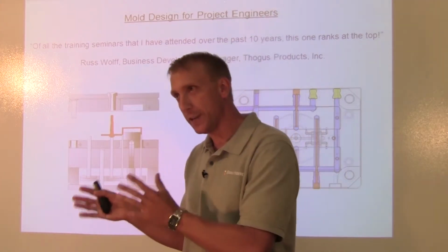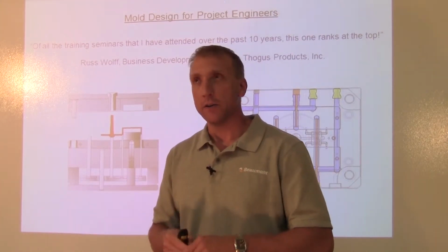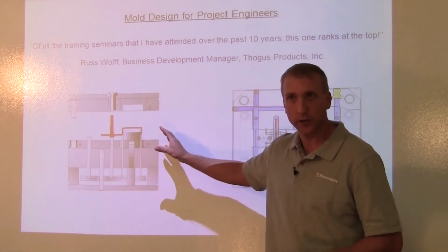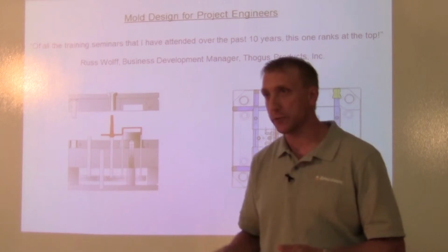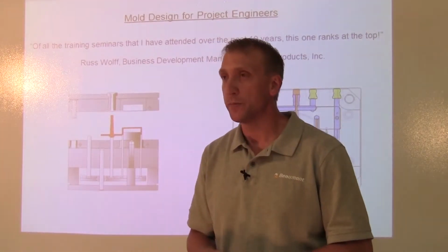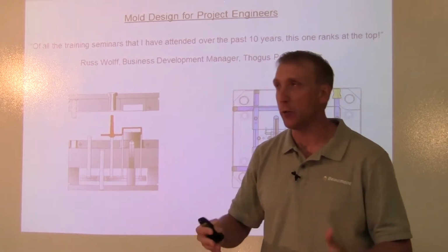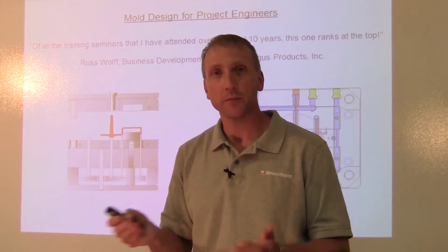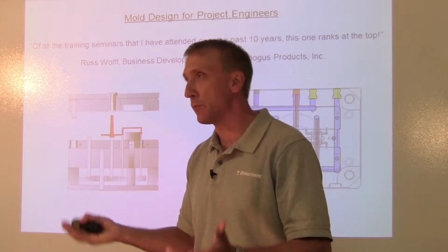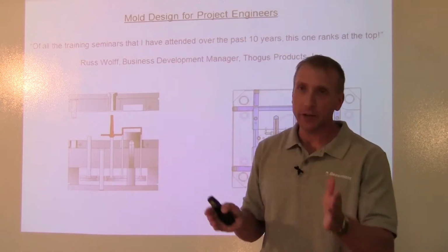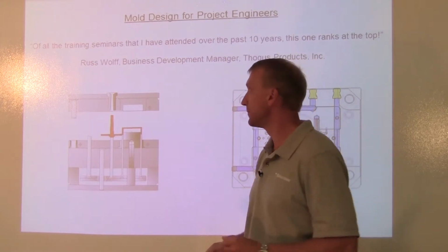And we focus on a key few areas that unfortunately in our industry seem to be often misunderstood or unappreciated, in particular the cooling system and the melt delivery system. And we give our students a little bit more insight into there and things to consider and watch out for in their mold designs. So when they're sitting down and reviewing a project, that hopefully they can pick out some of these things and eliminate downstream problems.